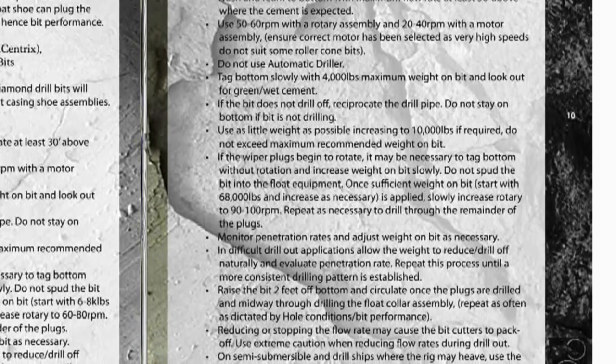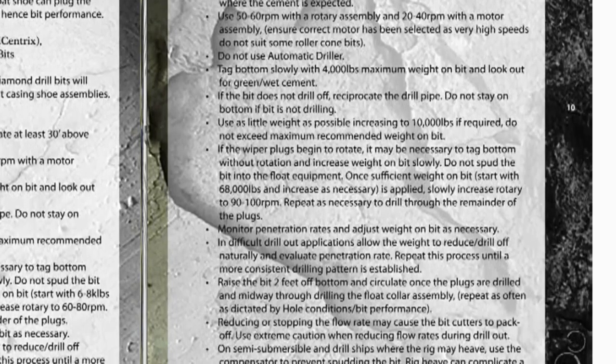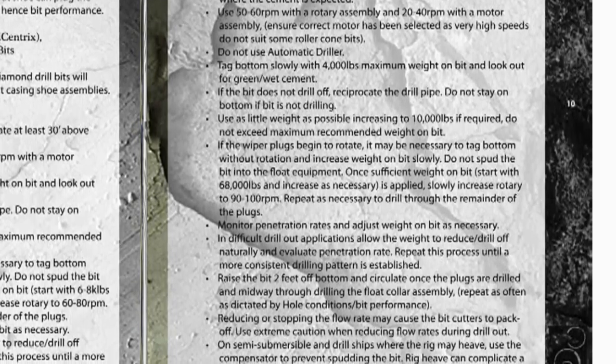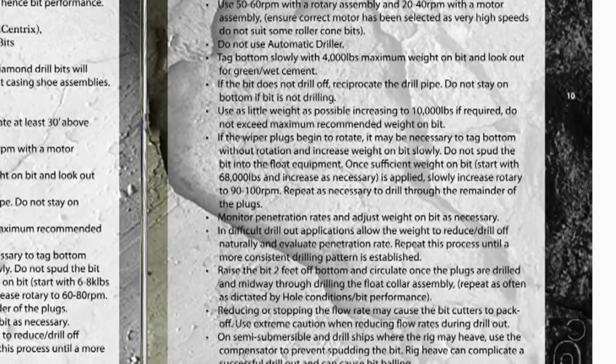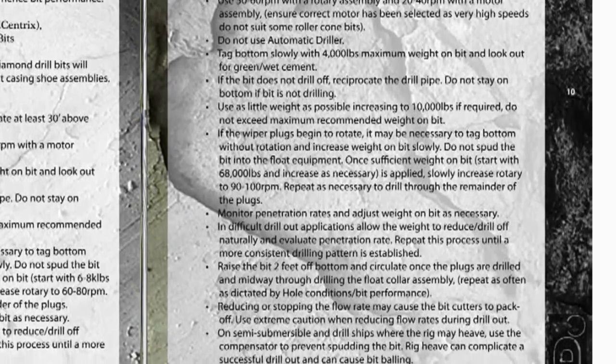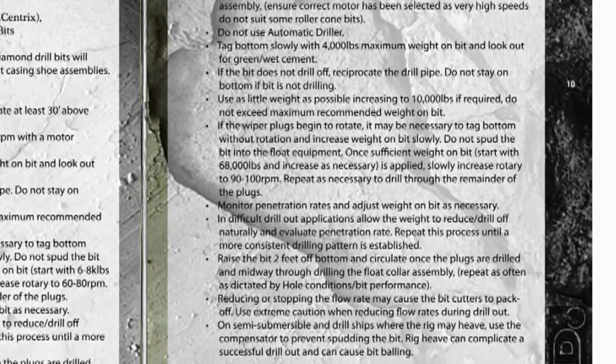Monitor penetration rates and adjust weight on bit as necessary. In difficult drill-out applications, allow the weight to reduce or drill off naturally and evaluate penetration rate. Repeat this process until a more consistent drilling pattern is established.